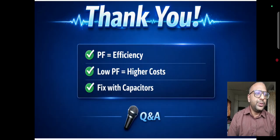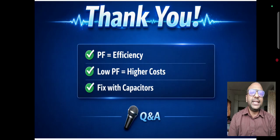That's all. To sum it up, low power factor costs you money and capacity. Fix it with capacitors, right sizing or correction devices.